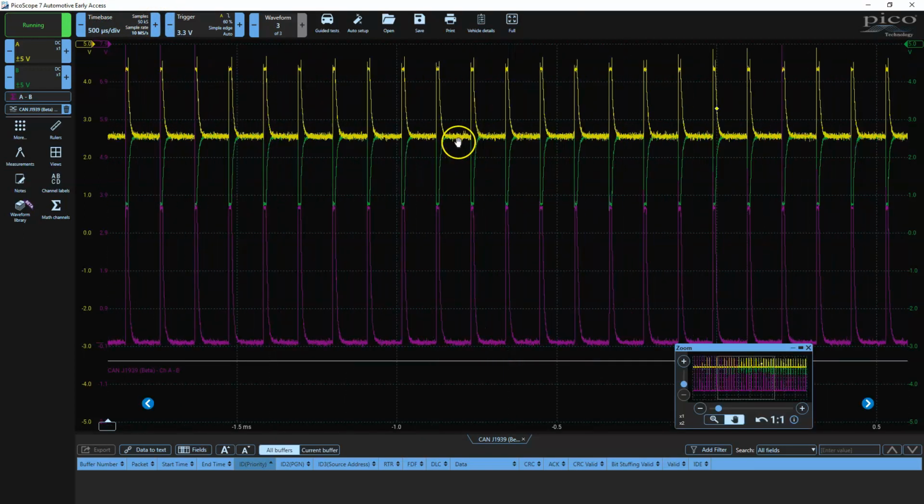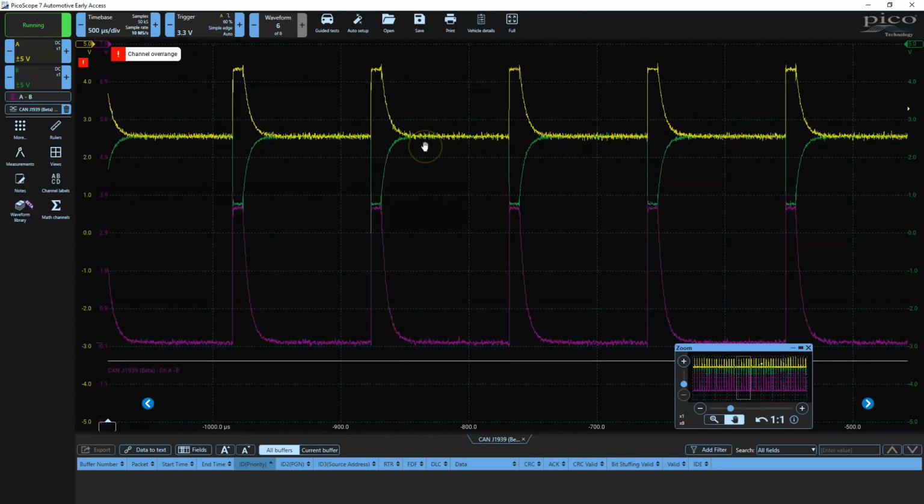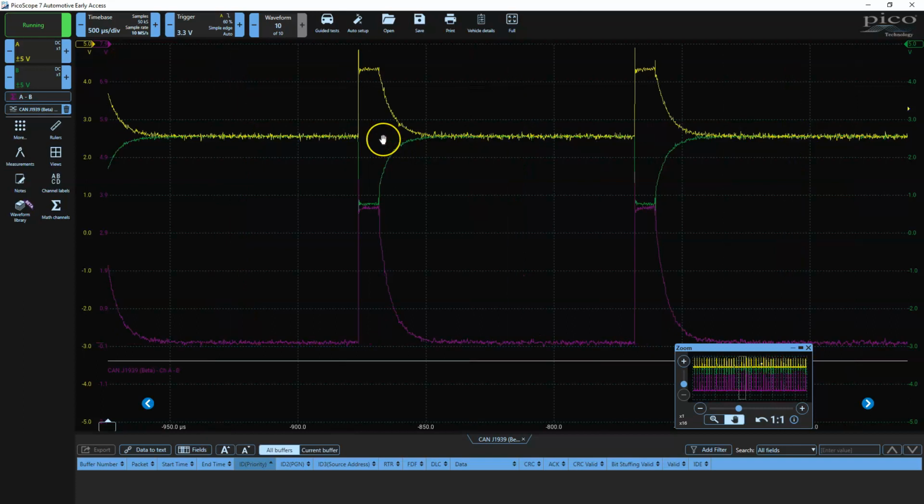And the reason it's dead is that this is more than likely the engine controller, or whichever controller it would be, trying to put a message out onto the CAN bus, and it feels that it's lost arbitration because, even though it's trying to drive its transistors to a recessive state, it is being detected as a dominant state. Therefore, it stops communicating because it believes it lost arbitration. Over here, it's like, oh, the network went quiet again. It's got sufficient time. I'm going to try again. You can see that's all that is occurring here.